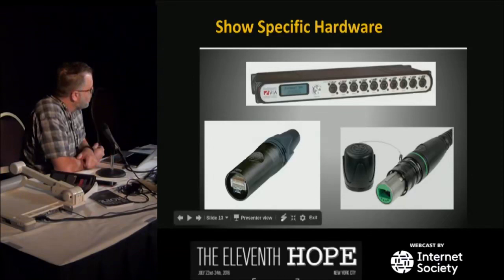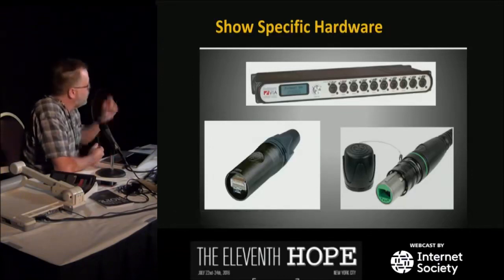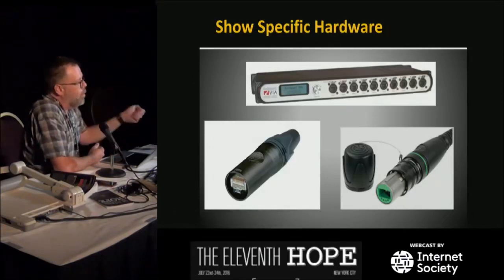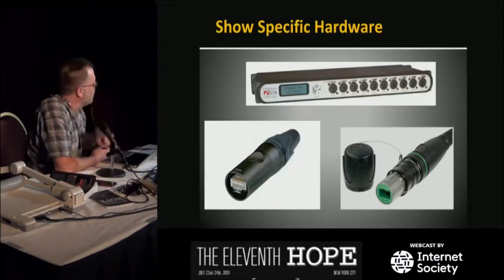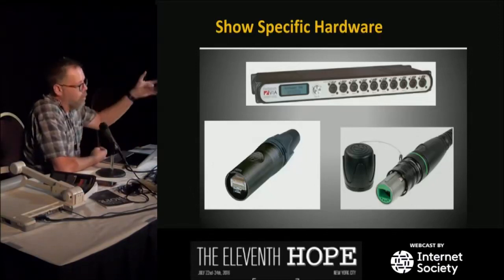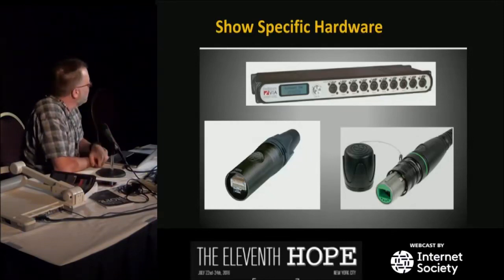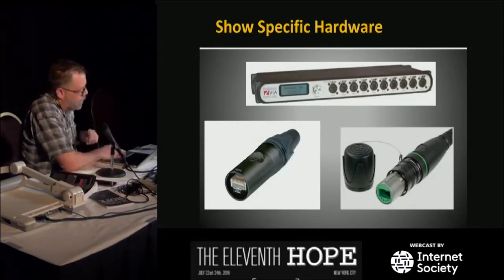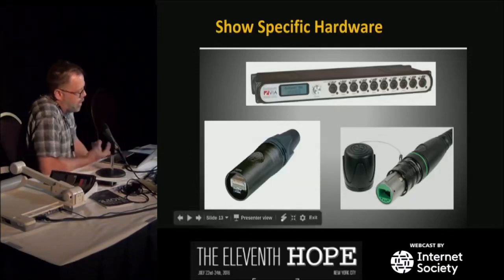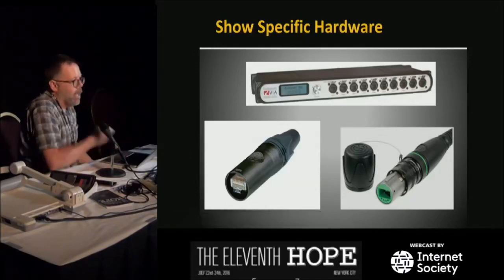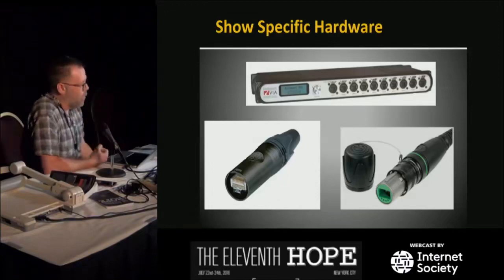That's a standard RJ45 connector that fits inside of a shell that's the same size as an XLR connector, which is what comes out of this microphone. So we already know we have panels punched this size, all this kind of stuff. Now we also have that same company, Neutrik, making a similar thing for fiber. So that's a dual fiber connector, a heavy duty thing that's easy for us to unplug and plug.